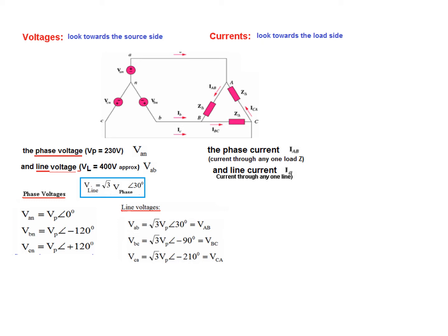Okay, now in this case, this voltage VAB is also equal to this voltage VAB. So that is why it is written VAB, VBC, VCA, but this is not always true. Like if there was an impedance here, then we cannot write that VAB is equal to this voltage, because there will be some drop here. So keep in mind that. Okay, and if we know this voltage VAB, then directly we can calculate the phase current, because it is voltage divided by impedance, so VAB divided by Z delta is IAB, the phase current, and similarly the other two.